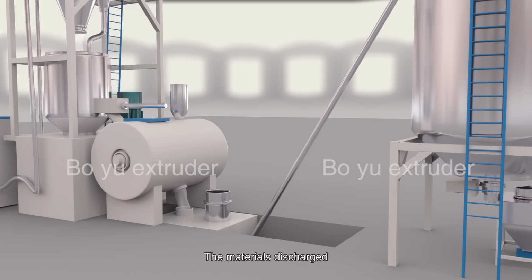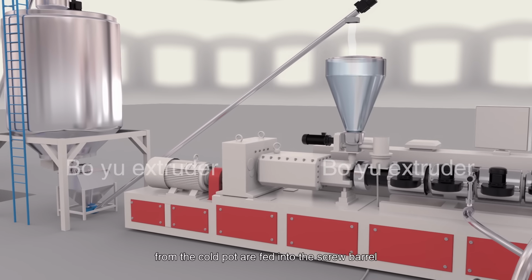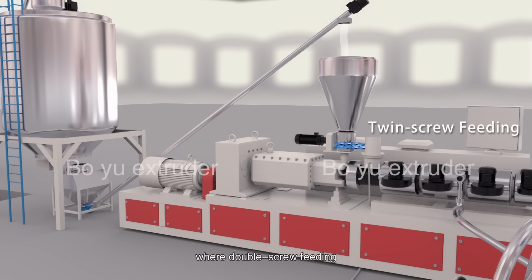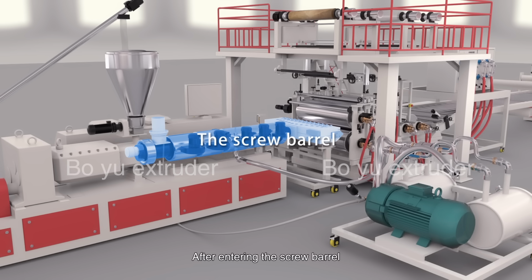The materials discharged from the cold mixer are fed into the screw barrel by a screw feeder at a constant speed, while double screw feeding can avoid the influence of starvation or stoppage of the feeder on the stability of the feeding process. Extrusion system. After entering the screw barrel, the materials are plasticized by heated rolling.